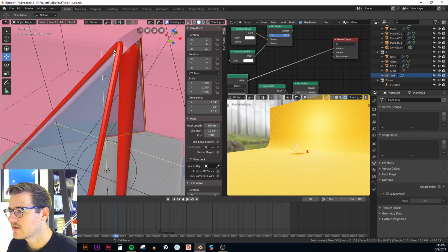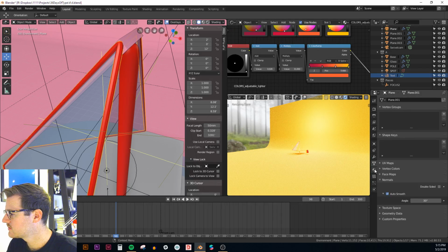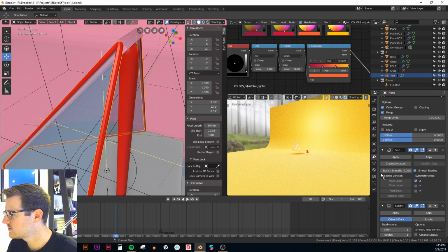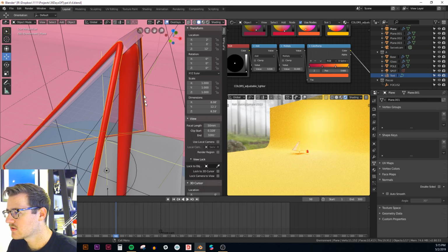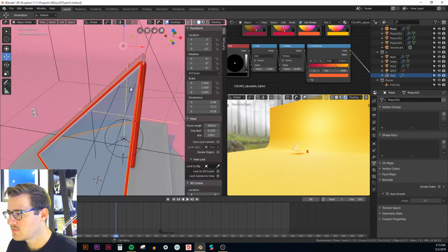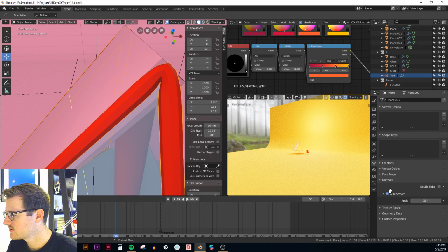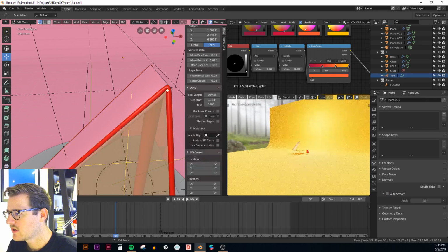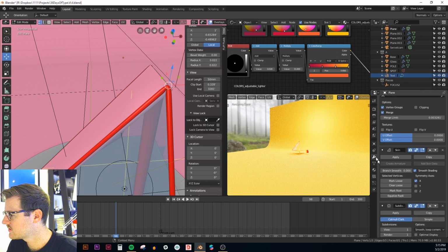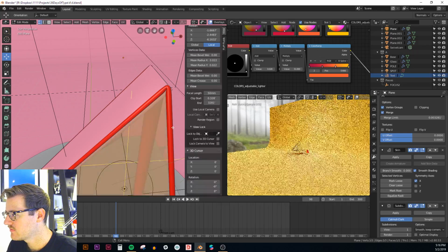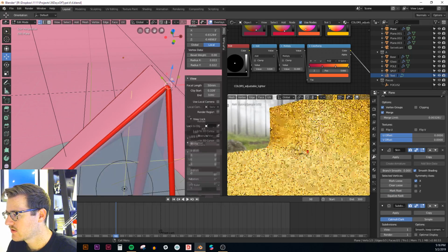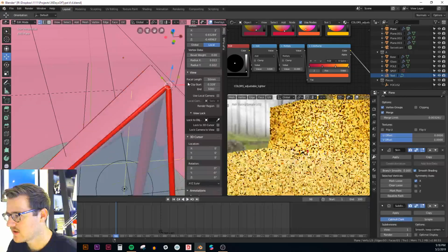Alright, so this little pinchy look up here is not cool. Let's first of all, oh, that is on smooth shading, auto smooth. I usually don't leave these panes too detailed, so they don't have a whole lot of vertices around the outside, so sometimes my auto smooth catches some edges, so I just turn it off, keep the whole thing smooth. I wonder if there's a good way to avoid this pinching, if there's an effect in here. Equalize radii? I don't think that does it. Let's just try, if we make this fatter. Nah, that's not gonna work.